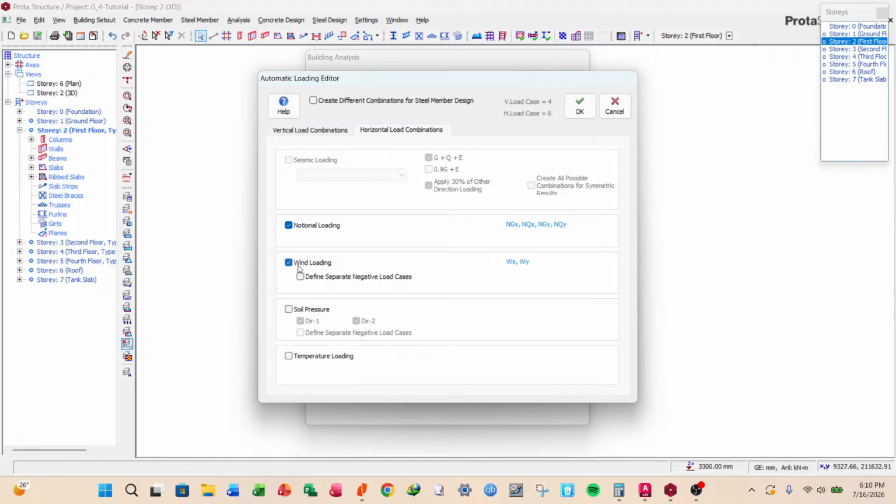When it comes to the behavior under wind, this building tends to act as a cantilever, and you know cantilevers deflect more at their ends. So this building will deflect more as the span increases, which this time round is the height of the building.